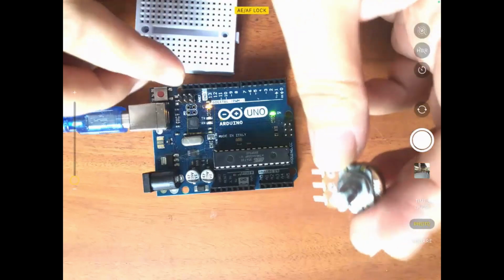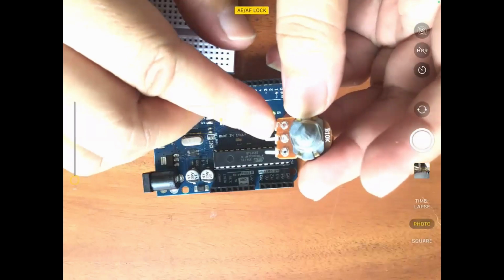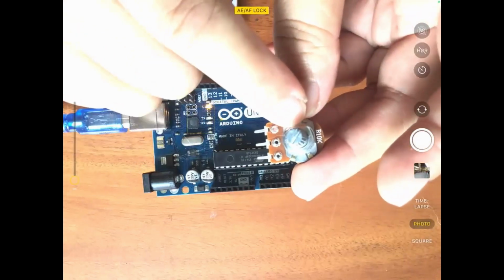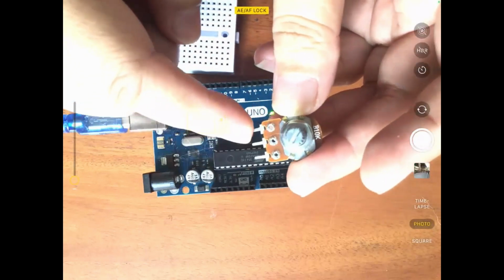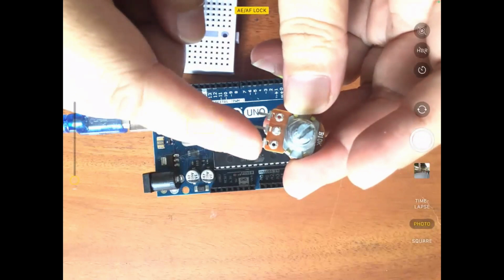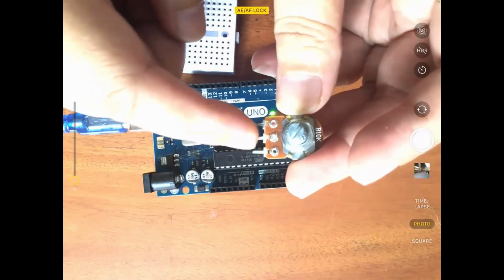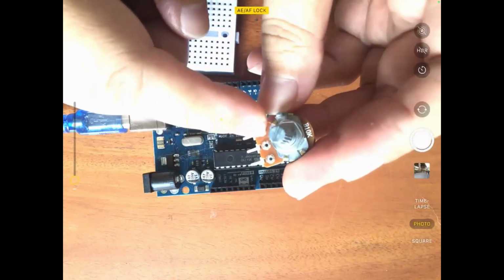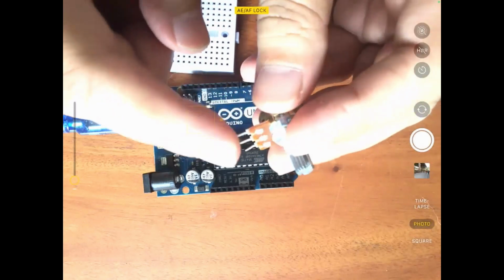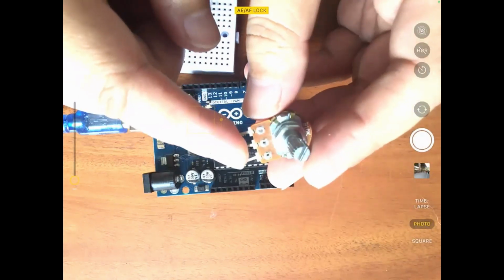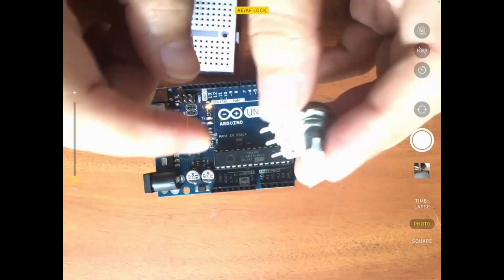Now, the thing about the potentiometer is it's actually an adjustable voltage divider. In this case, the maximum is 10 kilo ohms. These ends could either be put to 5 or ground, and they're interchangeable. And the middle part is the signal or the output part. This one divides the resistor into 2. If you tear open a potentiometer, it's actually a coiled or torus-like wire wound in a coil, which is formed into a donut shape.